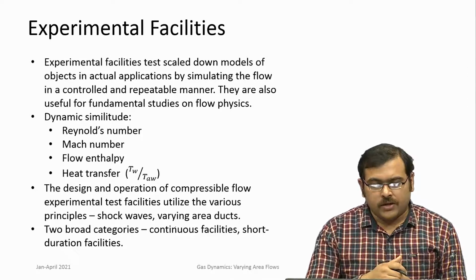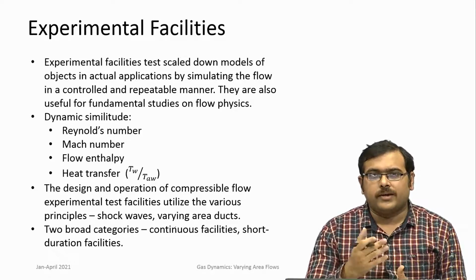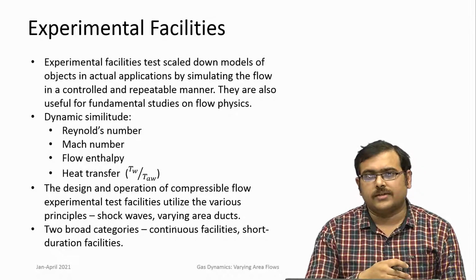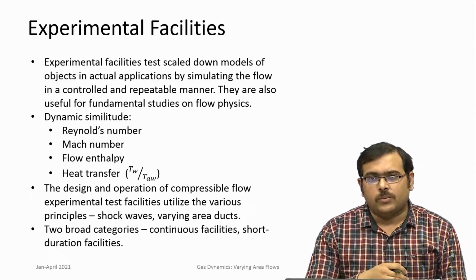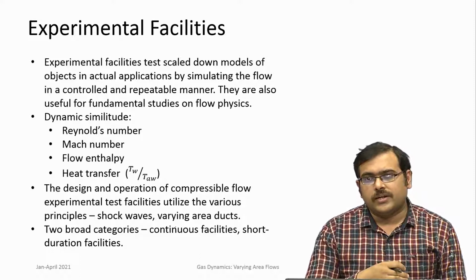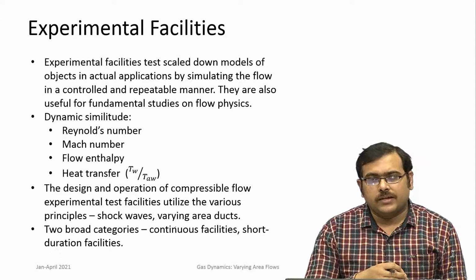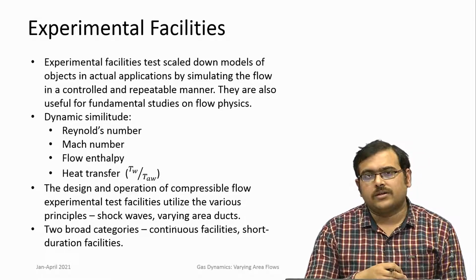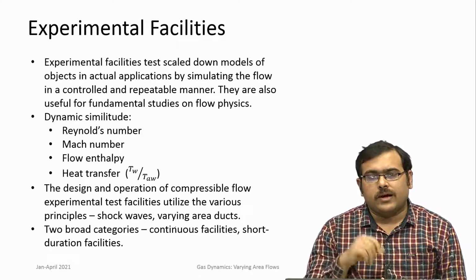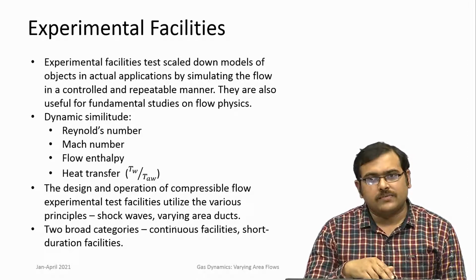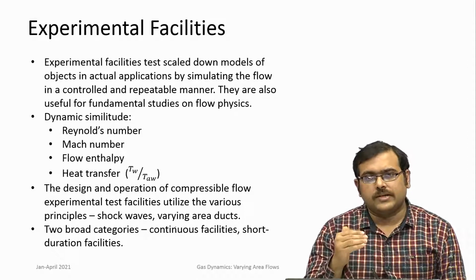Okay, but they are all very big, so you cannot test them directly in wind tunnels, very difficult because of their size. So usually their size is scaled down, and we also use the approach that instead of having the body moving at a particular velocity, we keep the body stationary and allow the flow to happen at the same Mach numbers that the body is flying.